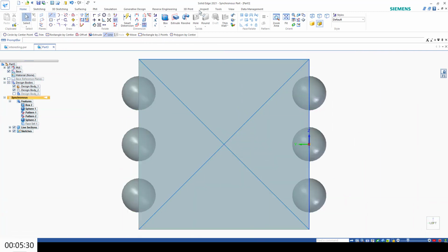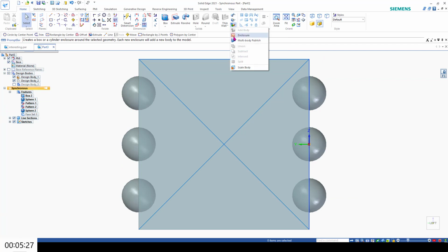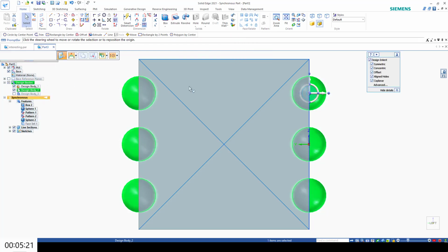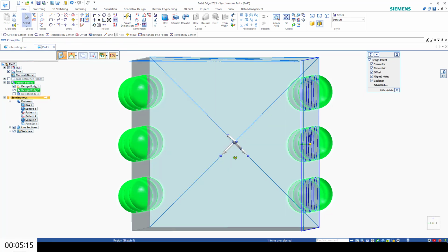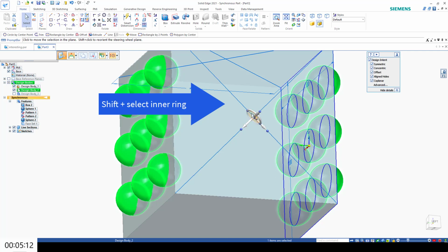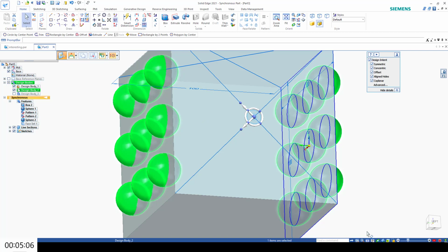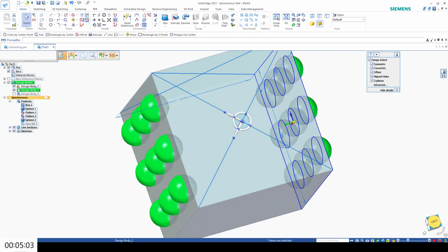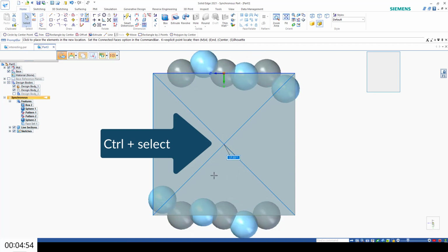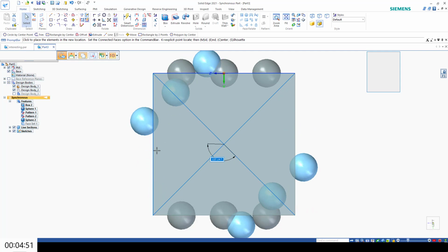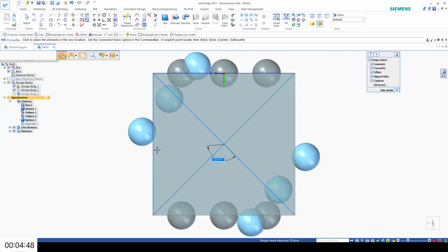All right. So add body. Oh, okay, we're in the command. Great. Select design body 2, my bad. And I'm going to bring it into the center of this face. Shift select on the center of the steering wheel to change its orientation. And rotate it by 90 degrees. So I'm just typing in 90 here.